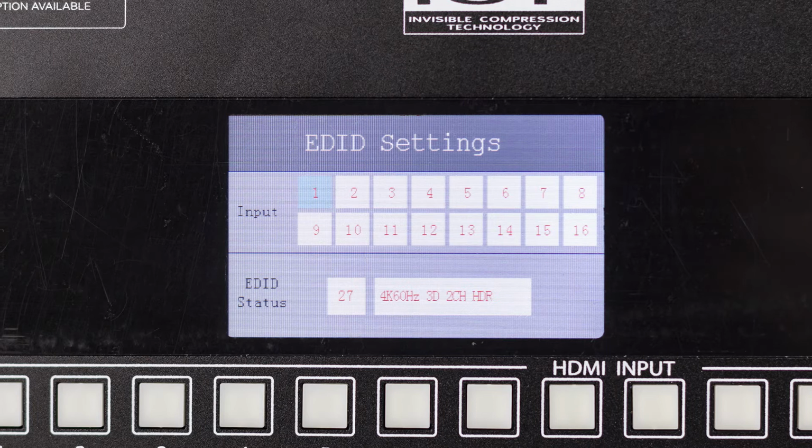To set the EDID, choose the EDID from the home screen, select the input that you want to set the EDID for, toggle through the EDIDs until you find the one that you want. For the most plug-and-play compatibility, we recommend using 1080p 2-channel. This is ideal for bars, restaurants, and even some homes.